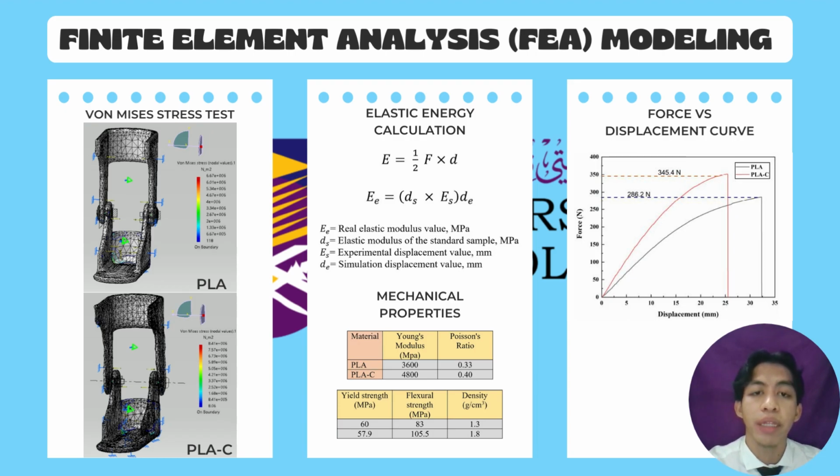Most complicated 3D printed objects have different modulus values than standard samples because the interior geometry is produced by the layering of materials, which makes the structure distinct from the standard samples. The second equation was applied to actual modulus calculations to generate the most accurate prediction and integrated into the simulation process. The equation, which was also applied in the earlier studies on orthosis, was derived from Hooke's law of proportionality.